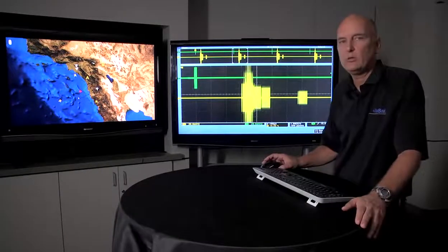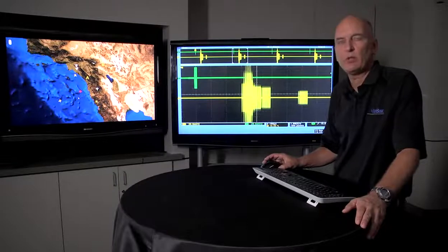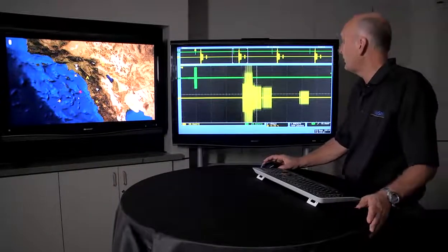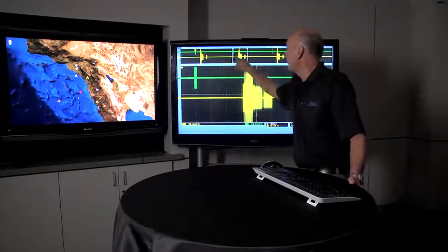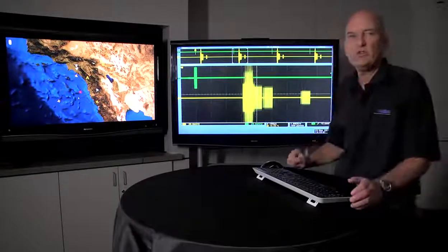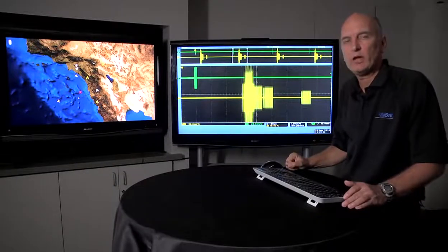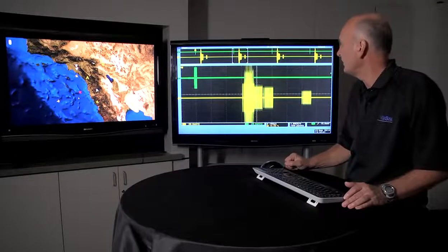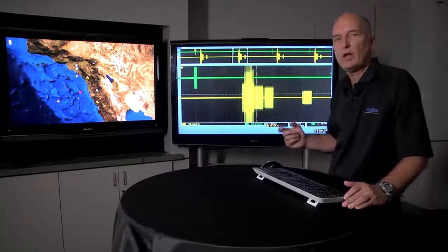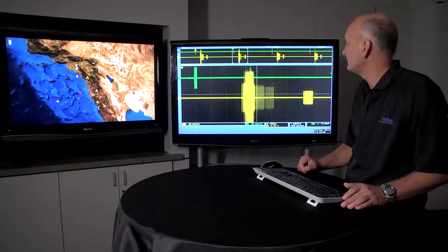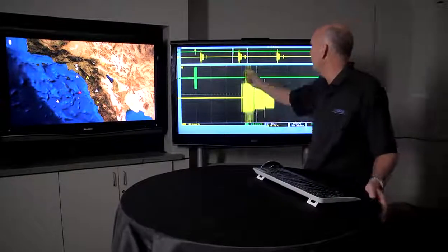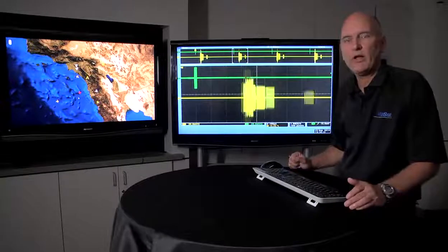With Mode S, we can receive in the interrogation the probability of reply, which will tell each independent transponder to reply at a certain probability. Right now we're responding at 100%, so you can see with each interrogation, all the platforms are responding to each interrogation. If we change the probability to reply to 50%, then you should see each platform only reply randomly half the time. There you go. So you see on average, each one's only replying half the time.